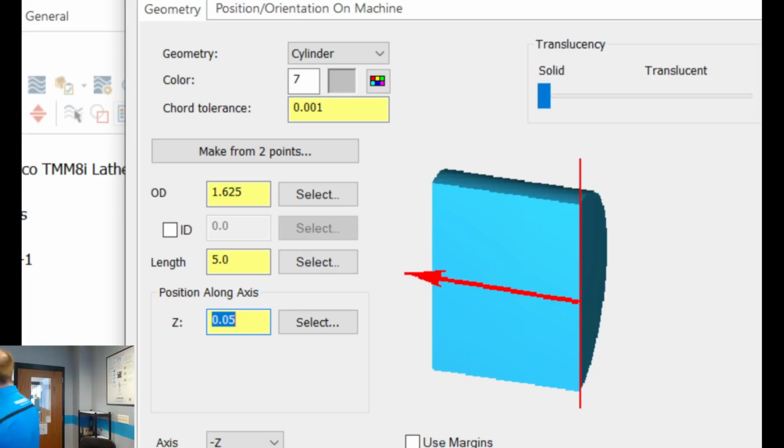We've got tube liners coming. Has anybody ever worked with tube liners on lathes, on CNC lathes? You know what I'm talking about? So we've got tube liners coming. We've got a company that reached out to me here recently. He's going to send us all these different size tube liners for the lathes out there, which what they do is you stick them inside the spindle tube, and they keep your material dampened to where when it ramps up to higher RPM, you don't get a bunch of vibration. So they just keep things concentric.